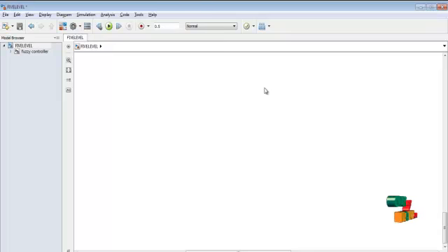In the simulation library browser, we mainly used 2 blocks, the SimPowerSystems block and the commonly used block. Those 2 blocks are used to arrange the elements as per the circuit diagram and to view the output waveform. After connecting the scopes from the commonly used block, the output is viewed there. Then click the run icon, and the output will be displayed in the corresponding scope.